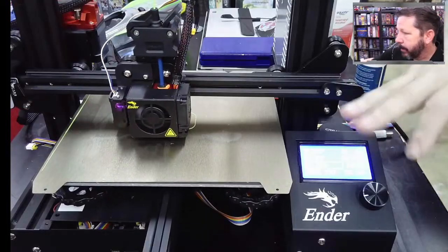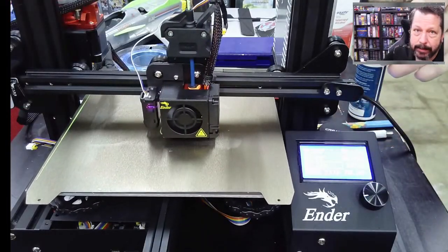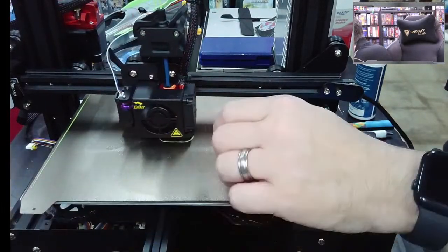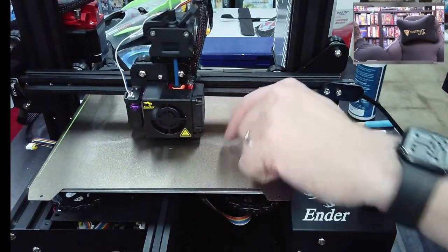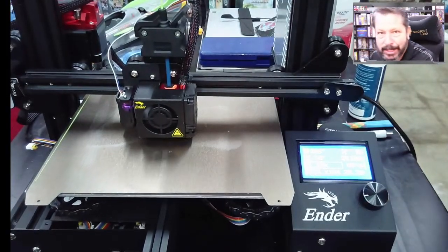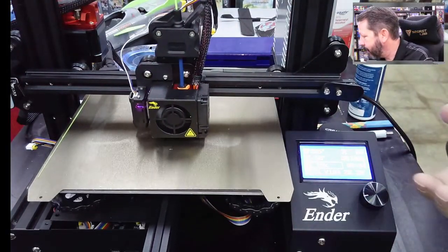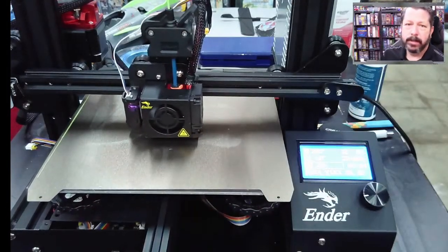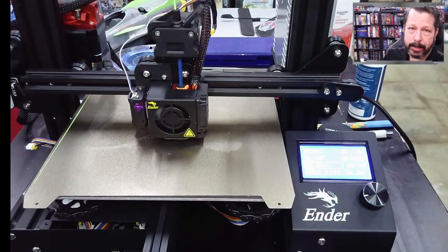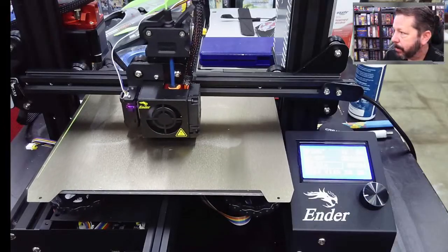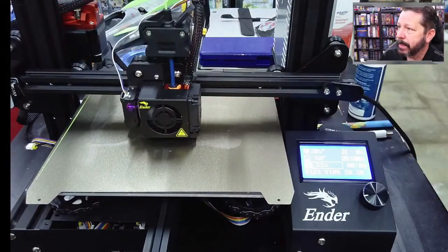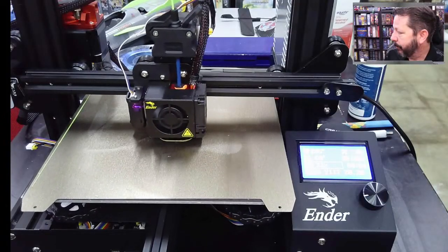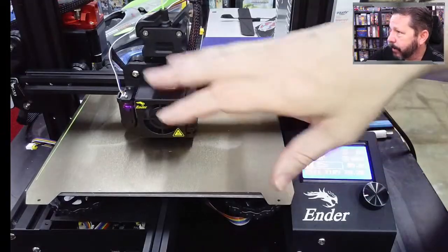And usually while these are printing, I'm monitoring it so that I can even go and flick the thing to make sure it's stuck down, because you have time to adjust the corner knobs if you find a corner is too high or too low. Most of the time, you're printing just in the very center of the bed, so you don't have to be that accurate. Very rarely, anyway, are you using the whole bed to print.